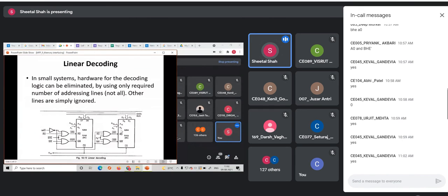The address lines connected to this IC are A1 to A13, because it is 8K. Now A14 to A18 are not utilized; they are don't care. You can use any addresses. Do you agree to this? That means if A19 is 0, irrespective of whatever the bits of A14 to A18 are, it would select these two RAM ICs. Followed?